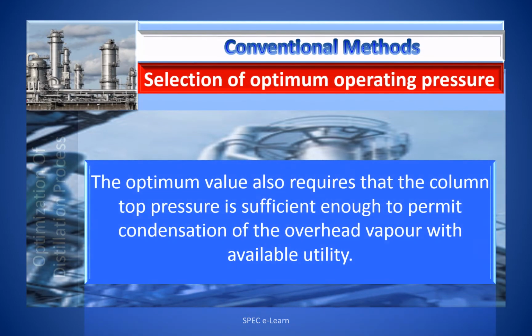Optimum value also requires that the column top pressure is sufficient enough to permit condensation of overhead vapor with the available utility.